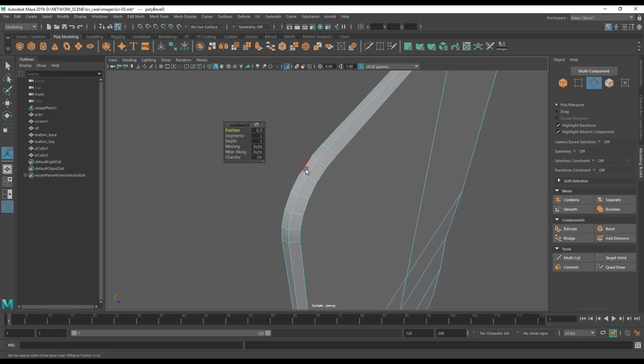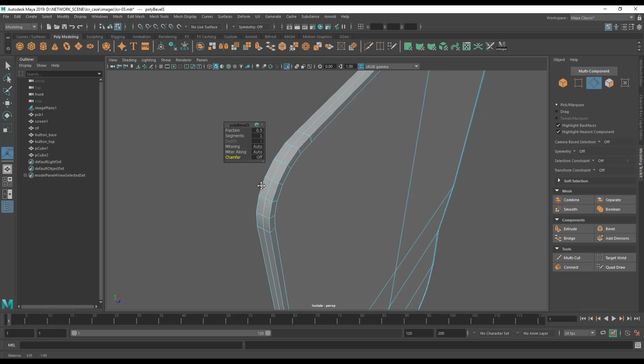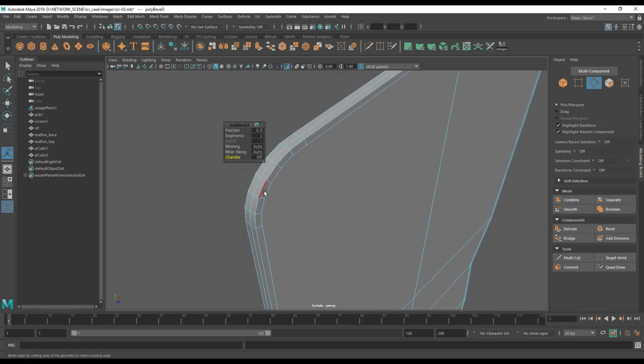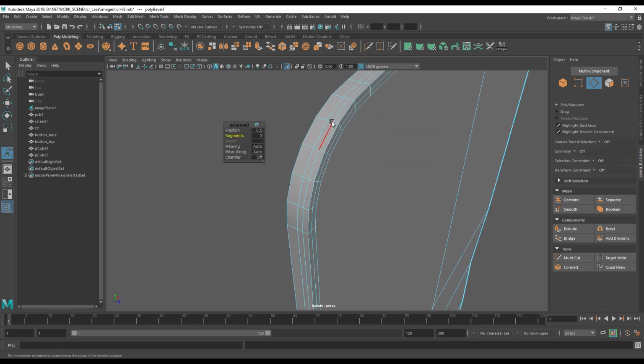a beveled edge on, but it's also put a chamfer on there which we don't want, so middle mouse drag that to off. And I also want 2 edges, so I want to extrude this twice so the case locks together. So instead of segments being 1, I'm going to go up to segments being 3. I'm then going to get rid of both of these 2 edges. Now there is a method in my madness.